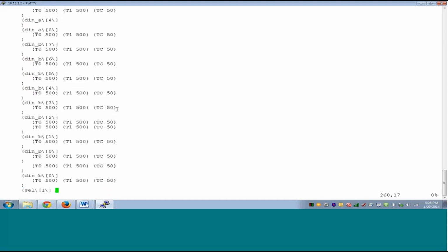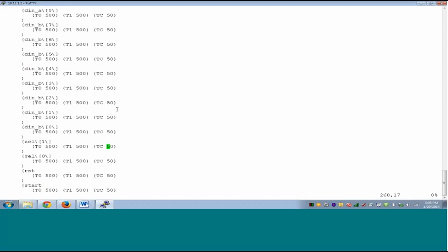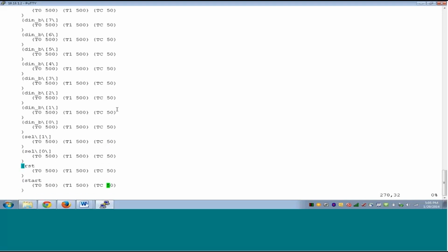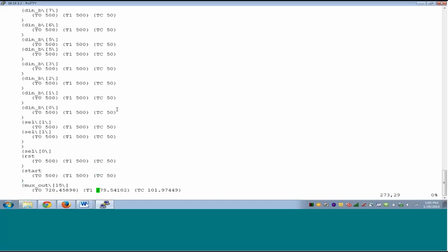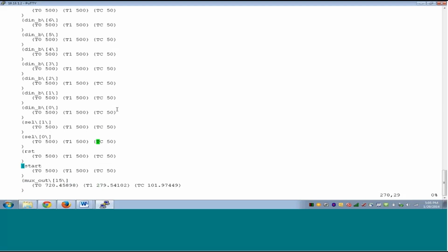Now these are primary inputs, right? Even here the reset also has a toggle rate of 0.1, but you probably don't want that. If you want to work with default values, please make sure some signals stay static, or toggle once you set the appropriate values. You can use set switching activity to set appropriate toggle rates.